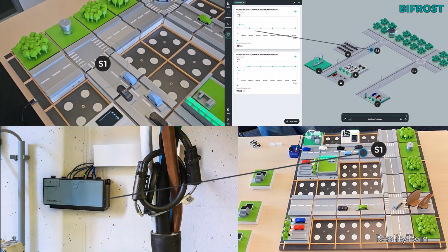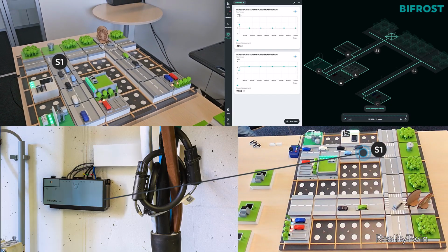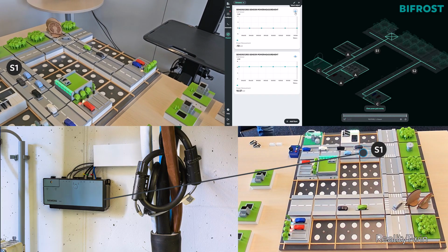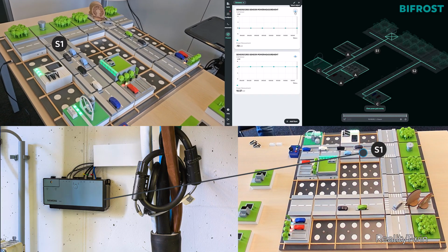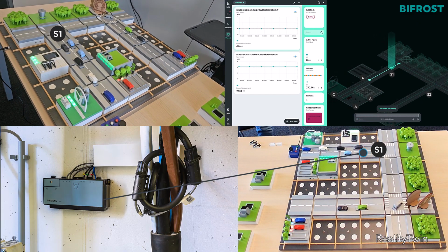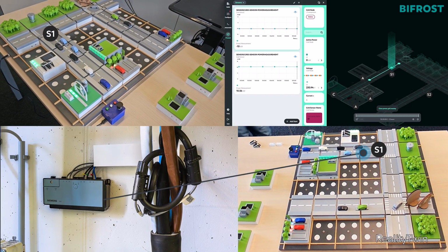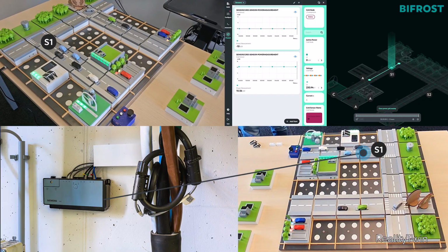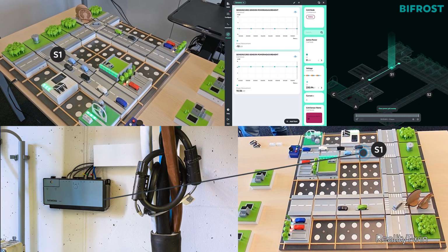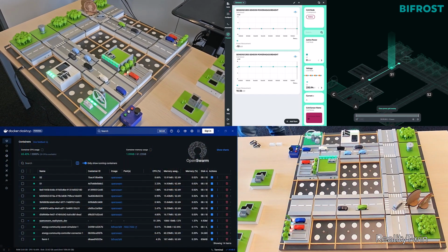This swarm is operated by the distribution system operator in the form of intelligent measurement devices installed, for example, here at the beginning of our feeder lines, where the wind turbine is installed. The sensor nodes have the task to observe the power over the asset, for example a cable, and ensure that certain grid limitations like a power limit are kept.